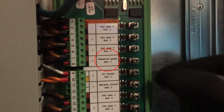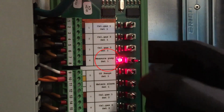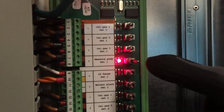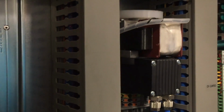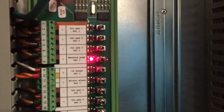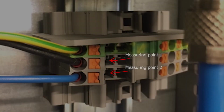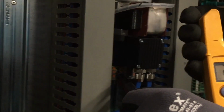Another possibility is to switch on the pump with the switch. The LED lights up, and the pump starts running. If not, you can check the power. The power should be checked here. Use these positions to measure the power. As you can see here, we are currently measuring the correct voltage.